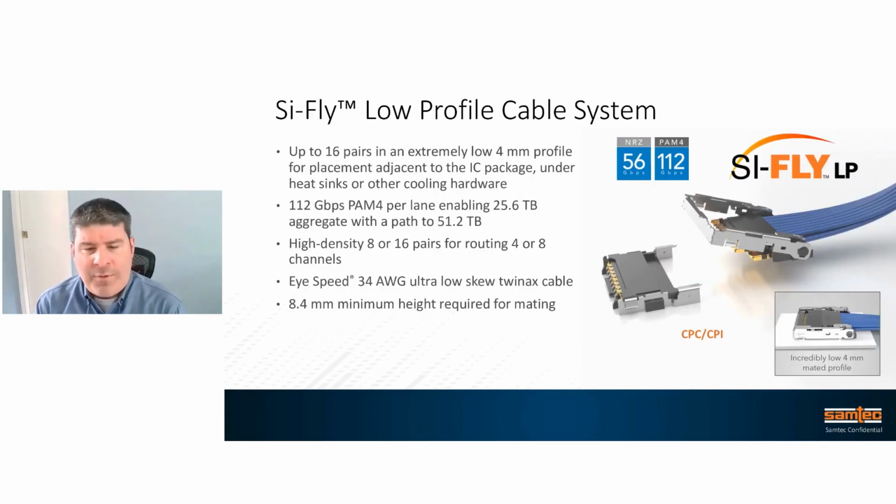Another solution that we offer that's ASIC adjacent but low profile is what we call our SciFly LP. This is targeted at sitting next to an ASIC solution. You'll notice that it has a very low profile, 4 millimeters. That allows the system to abut the ASIC on the system while also being small enough to sit underneath the heatsink.